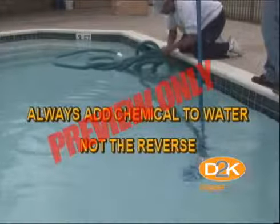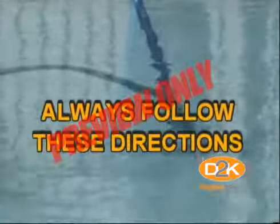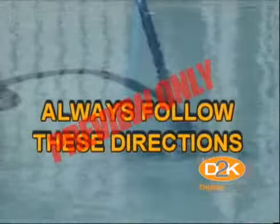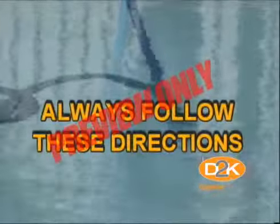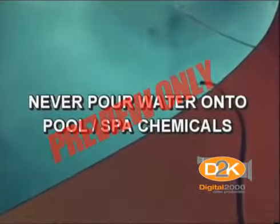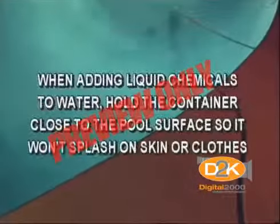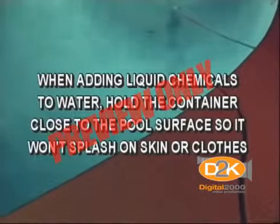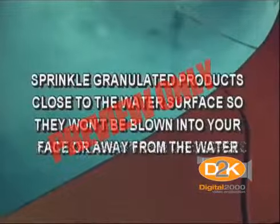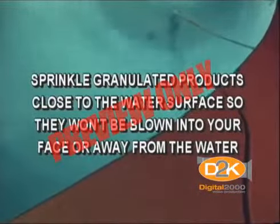Always add chemical to water, not the reverse. Always follow these directions. This will prevent staining or cloudiness and will ensure uniform distribution throughout the pool or spa in the shortest period of time. Never pour water onto pool or spa chemicals. Always use an oversized clean plastic container. When adding chemicals to water, hold the container close to the pool surface so it won't splash on skin or clothes. Sprinkle granulated products close to the water surface so they won't be blown into your face or away from the water.